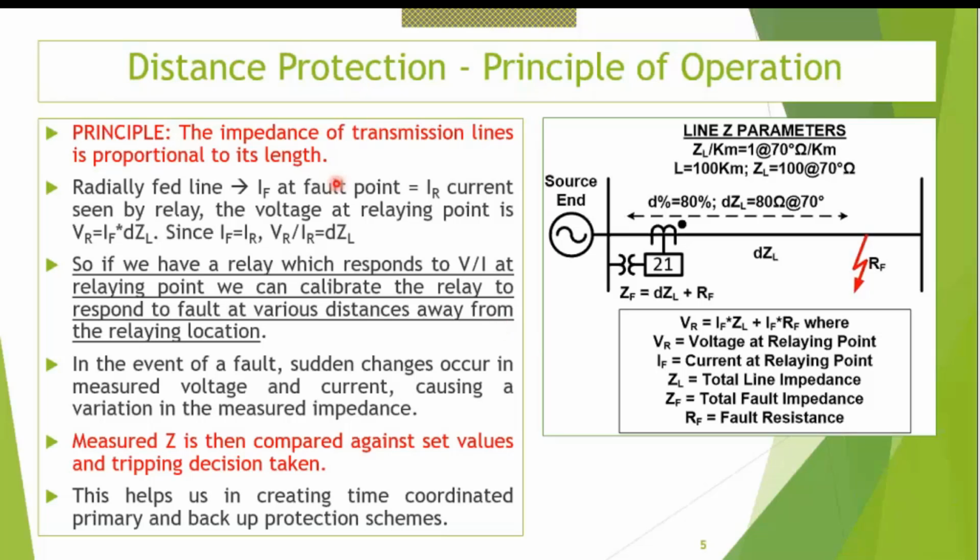Now, all these equations I have written over here are applicable only for a radial line. Distance protection works perfectly in a radial line. Wherever there is infeed, there is some source of errors. We'll talk about them later.